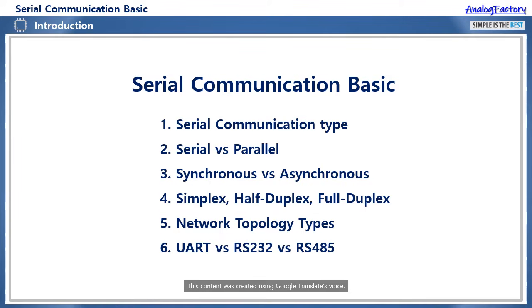Let's learn about serial communication, which is essential as a means of communication in hardware system configuration. In this lecture, we will look at the types of serial communication applied in the embedded field, basic concepts related to serial communication, and basic hardware applications of UART, RS-232, and RS-485.